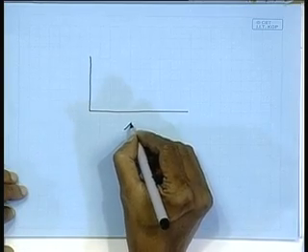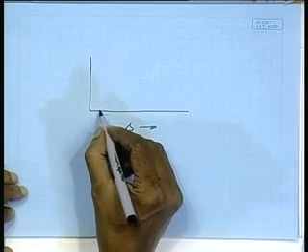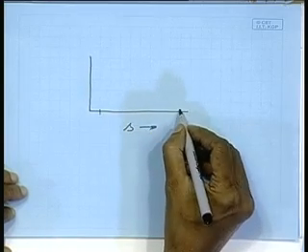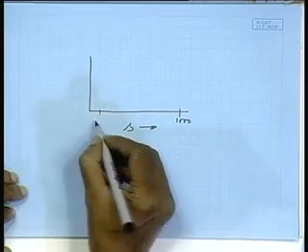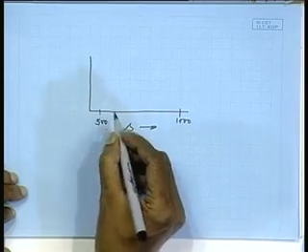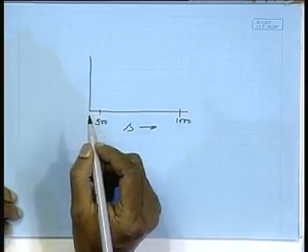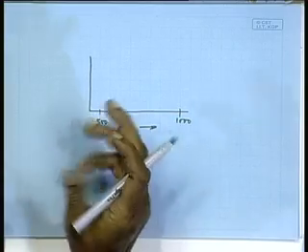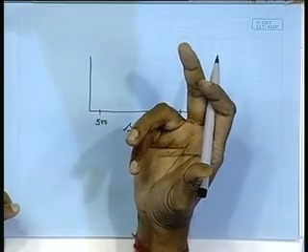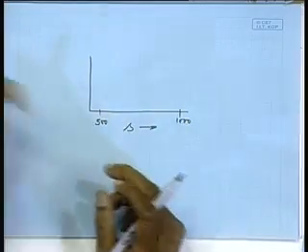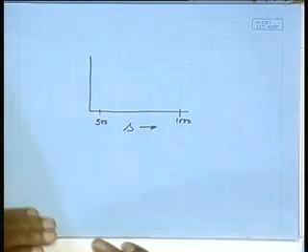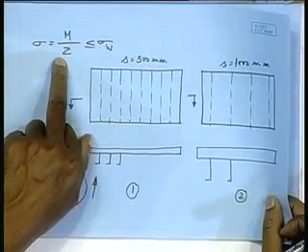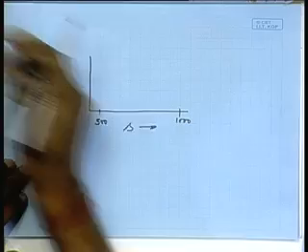Say various frame spacings, you have 500, 600, 700, 800, 900 and 1000 suppose. Instead of going by strength to weight ratio, I can straight away calculate only the weight. I have to minimize the weight, because strength is all the same, or nearly the same, because that criterion we have satisfied through this. So, straight away only the weight.